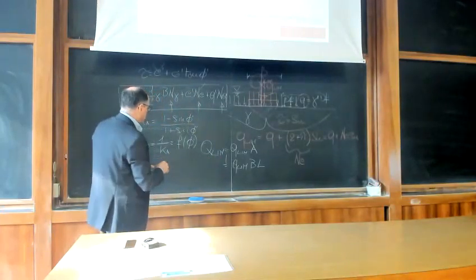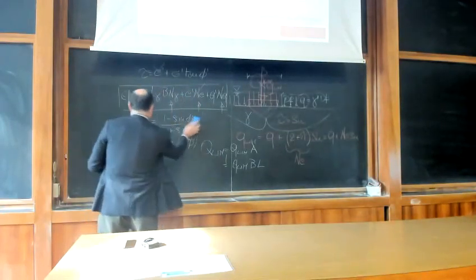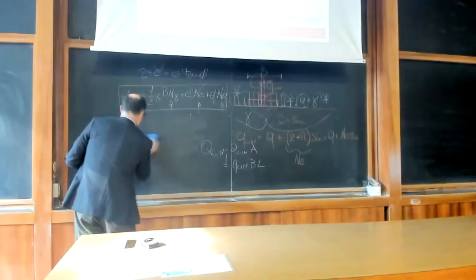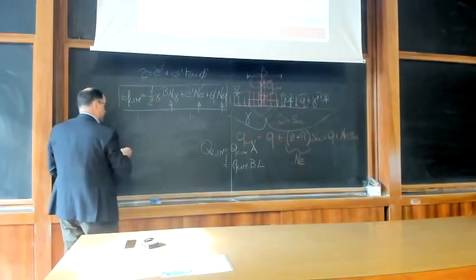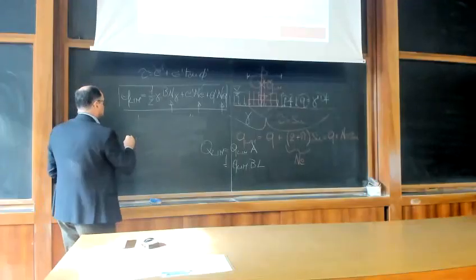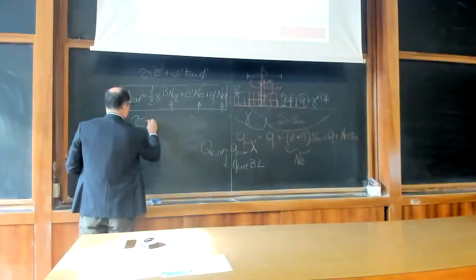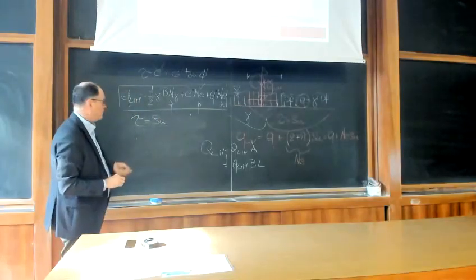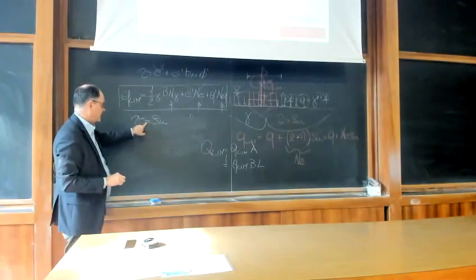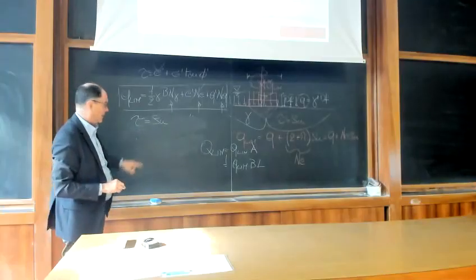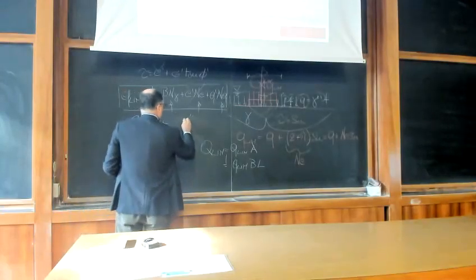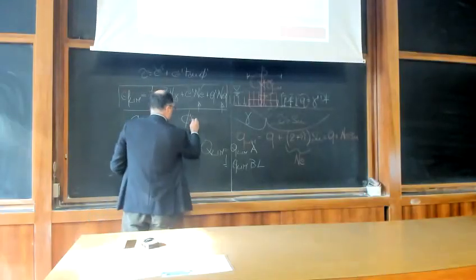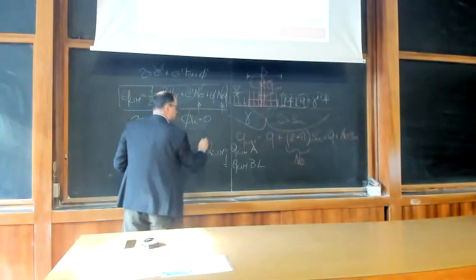Now, if you are in undrained terms, and we go back to our Tresca criterion, in which the shear strength is expressed as undrained shear strength, this means that your undrained shear angle, if you remember, is equal to 0.